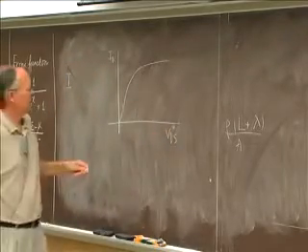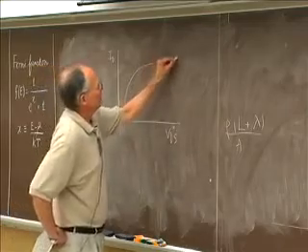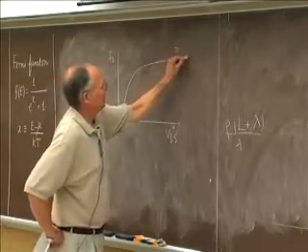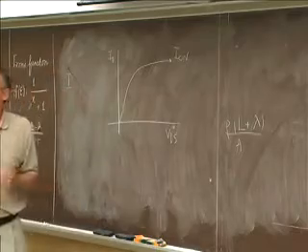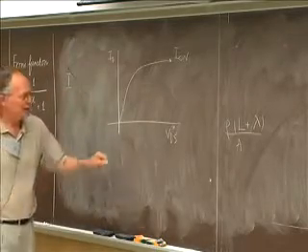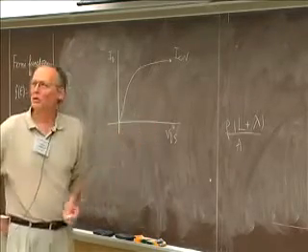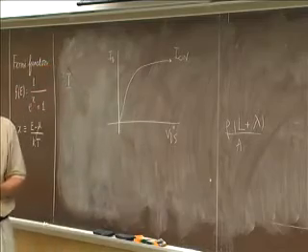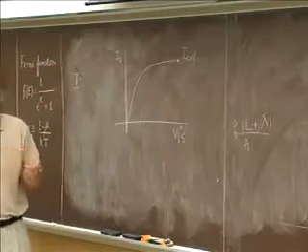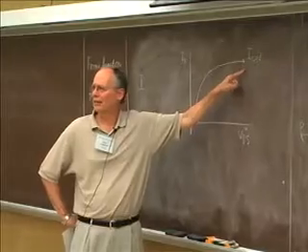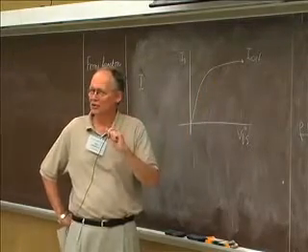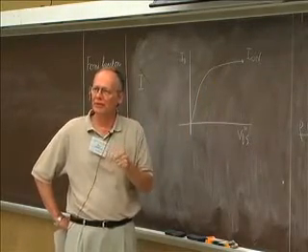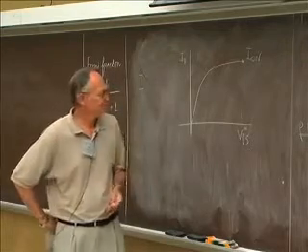When you make a transistor, the transistor people would like to have a lot of current when the device is on, at a given voltage as low as possible, a volt. If you could do a half a volt, it would be even better. You'd like to get a lot of current so that you can charge and discharge all of the capacitances, do the wiring and everything on the chip, and run very fast.